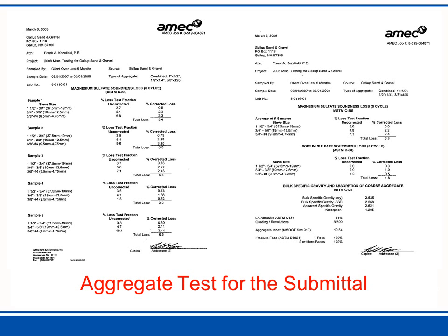Then every 6 months I would take the aggregates to the laboratory in Albuquerque, and we would do a soundness loss, and then we would do absorption, specific gravities, LA wear, fractured faces, and a lot of this information for the New Mexico DOT for their work. So these aggregate tests were used for our normal concrete mix design submittals.